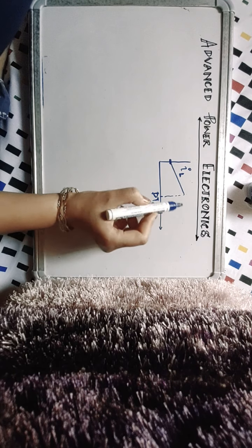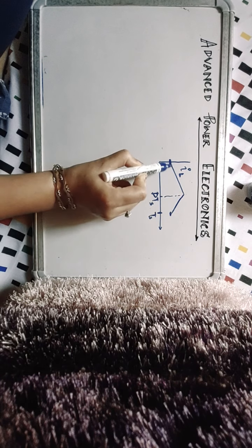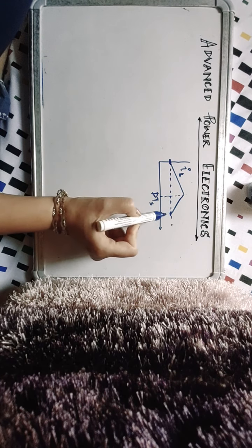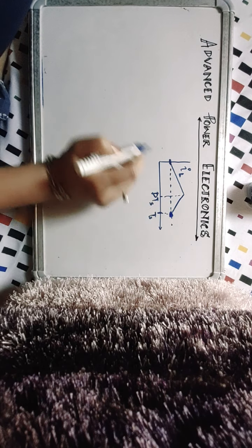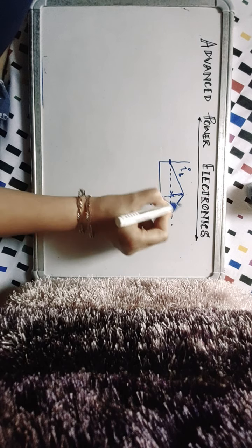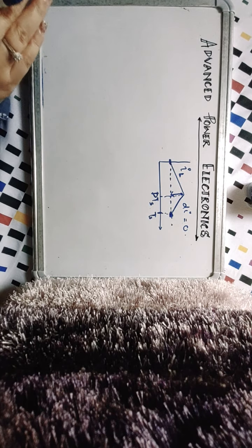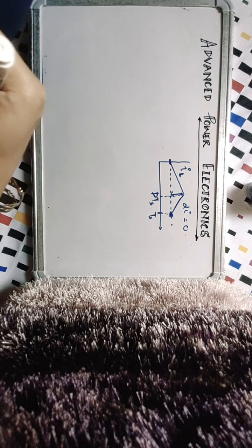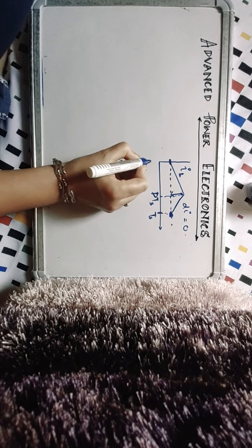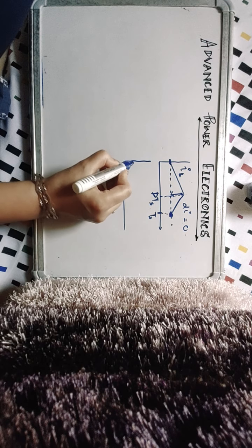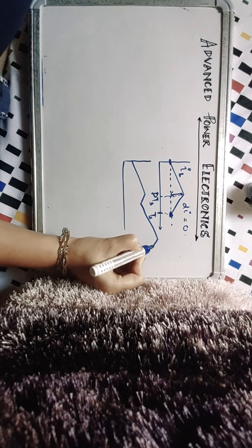If this interval is small, this inductor should release energy fast, so that after the completion of this interval, IL reaches back to the same value and there is no net change in current. DI is 0. This is what it means that the inductor has released all the energy that it had previously stored. If it is not able to do that, what will happen? The inductor will burn out. Say it stores energy, then releases only some, then stores, then releases only some.